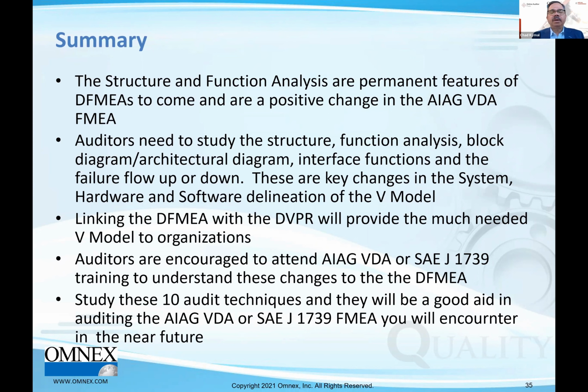All right, there's a V model I didn't talk about. But what we're doing here in the structure and the V model is very linked. Linking the DFMEA with the DVP&R, this is a big deal, and I'm talking about this a lot, is the way to do the V model. Auditors are encouraged to attend AIAG-VDA SAE J1739 training to understand the changes to the DFMEA.